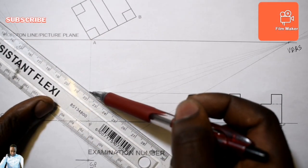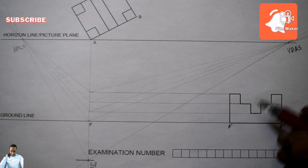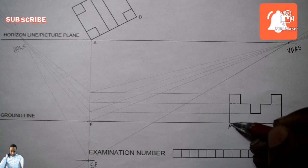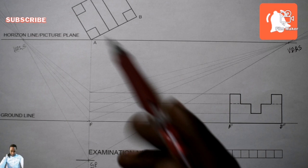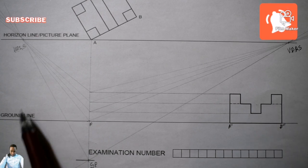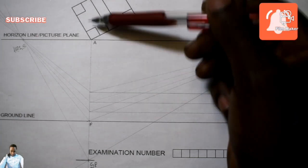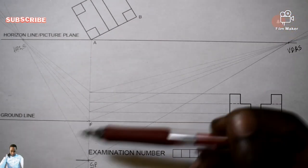Like this I can go. Right. So now, from my right view, this is the right view. This was given according to third angle orthographic projection, because if it was given according to first angle orthographic projection, this was going to be on the other side. So what separates the right from the left is this vertical line, you understand?